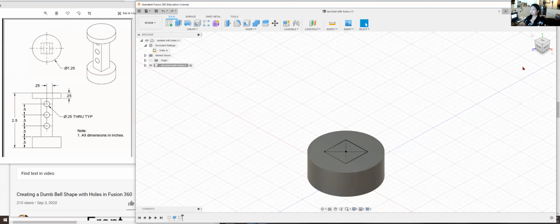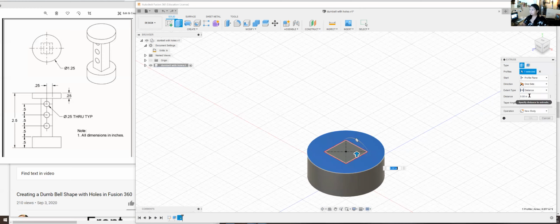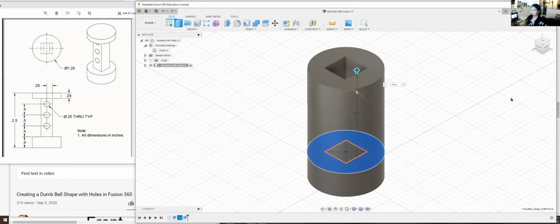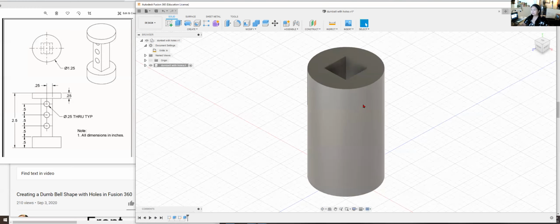So if you click on the top, if you click on just this, right, and then you hit E for extrude, and then I type the distance 1.75, you end up getting a socket looking adapter, and that's not what you want to do. So that's why you want to highlight just the center sketch, which is the center rectangle, right? So let me undo that, right?